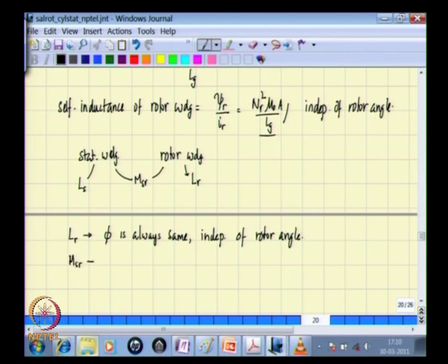In the case of the mutual inductance between the stator and the rotor, what we did was we excited the rotor and we tried to find out the flux density distribution. What we found was the waveform of flux density distribution around the air gap is the same irrespective of where the rotor is. It is just that the waveform bodily moves, but the wave shape remains the same. Now, that enables us to describe this flux density waveform in terms of Fourier series, and then we were able to arrive at the flux linkages.